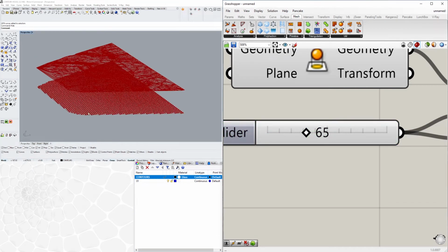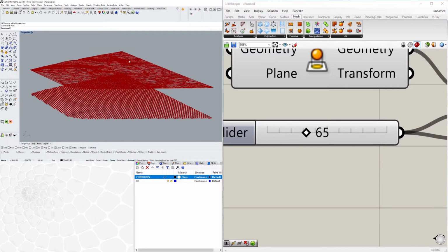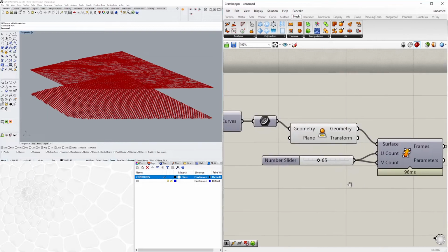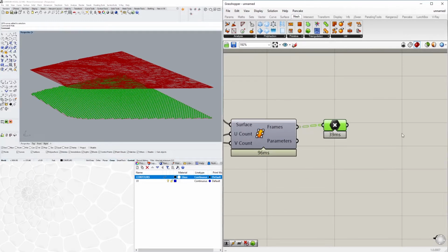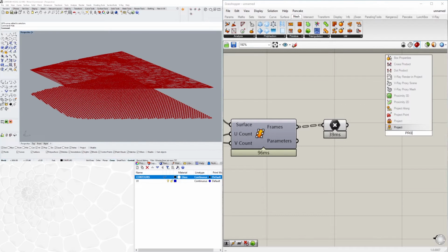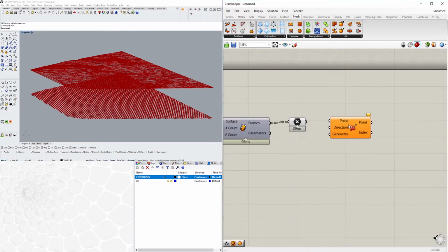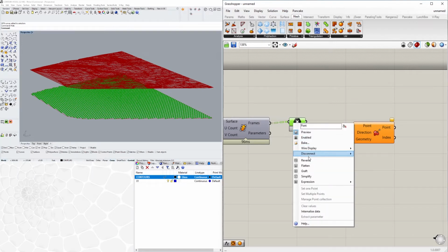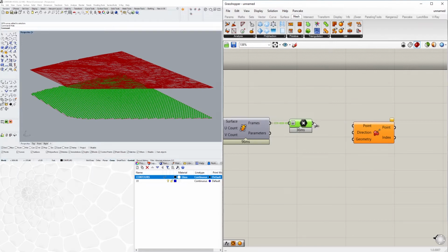And as you can see, what we're going to do now is project these points into this mesh that does not work. And so what that'll do is create a new set of points, and then we can turn that into a mesh. So let's take these points and let's project them. So let's go to project. On this one, it's going to be different. It's going to say project point onto collection of shapes. We'll take all of these points, I'll flatten them, and I'll plug those into the point.